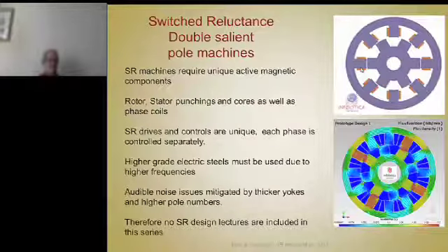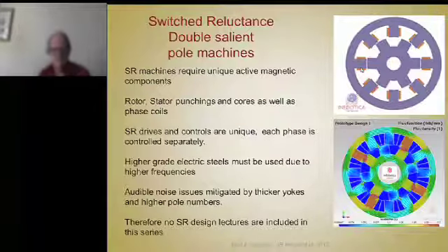If everything else is equal, same torque, same diameter, same voltage, everything, the one at the bottom is going to be quieter than the one at the top with the same yoke thickness. The deflection is way less. It's much stiffer because of the arc length between 90 degrees and 180. So the effective section modulus against that deflection makes it quieter.